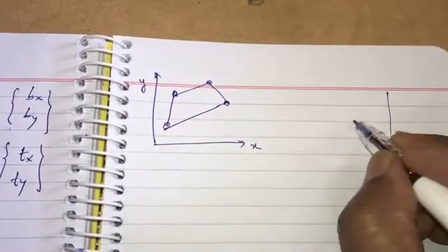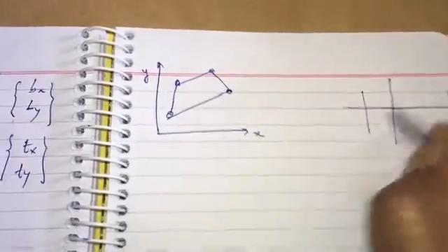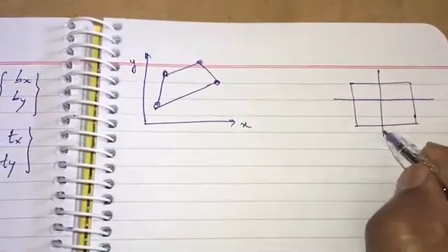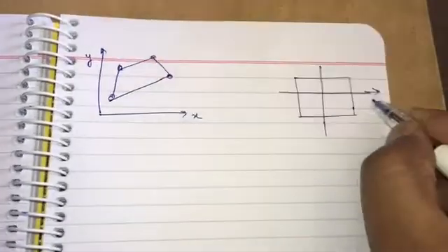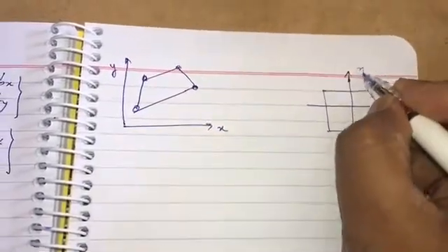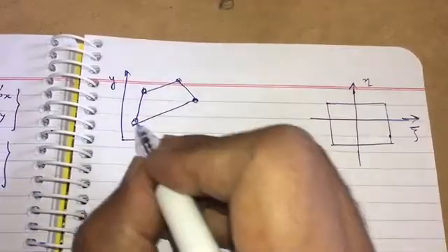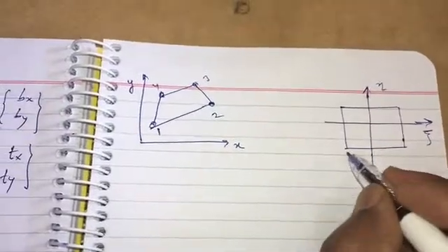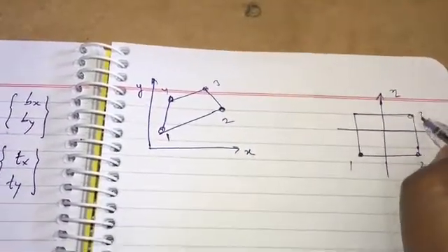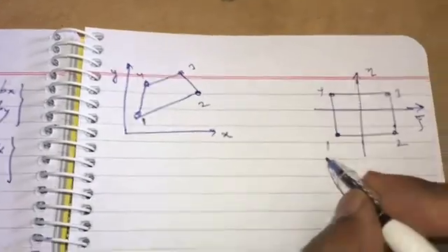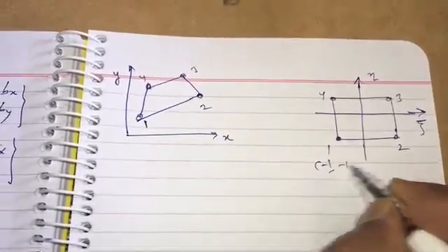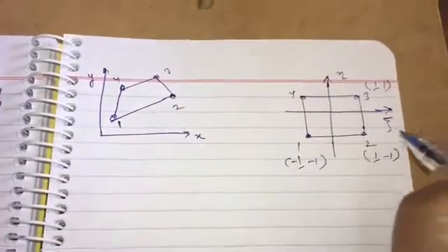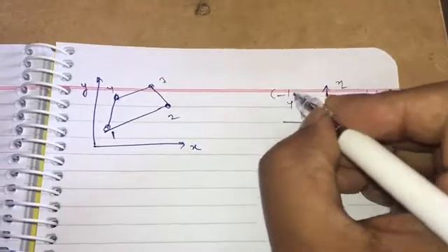So, we will have to convert basically from this irregular quadrilateral system to the xi and eta system that we have done earlier, such that let us say points 1, 2, 3, 4 become nodes 1, 2, 3, 4 here with coordinates equal to -1, -1, 1, -1, 1, 1 and here -1, 1.